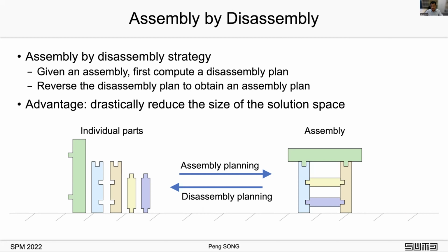The advantage of this strategy is to dramatically reduce the size of the solution space for searching the valid assembly plans. This is because parts in an assembled state have far more precedence and motion constraints than in the disassembled state.